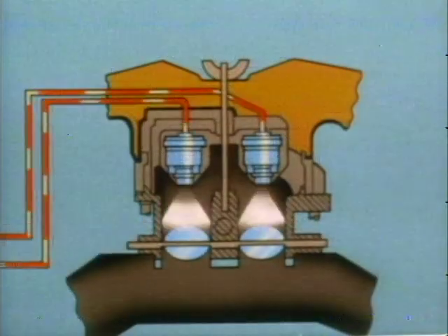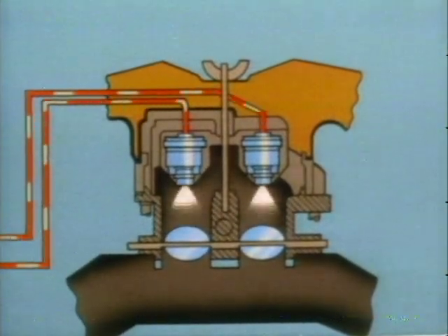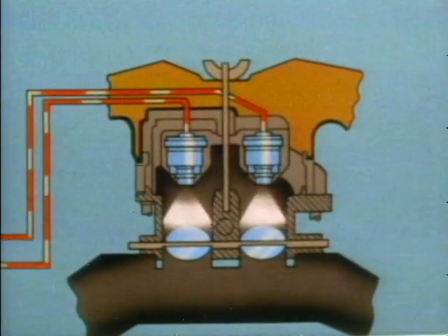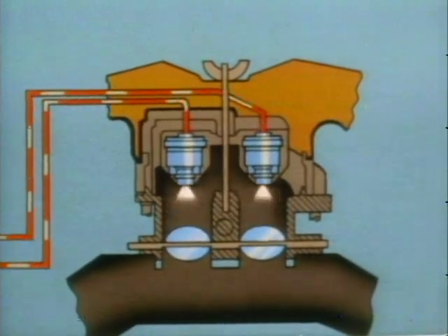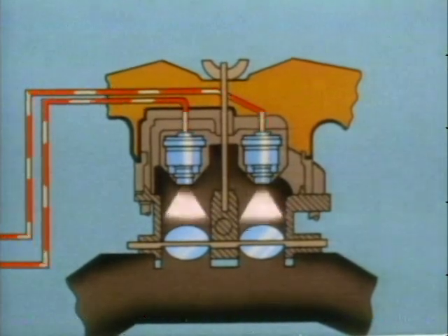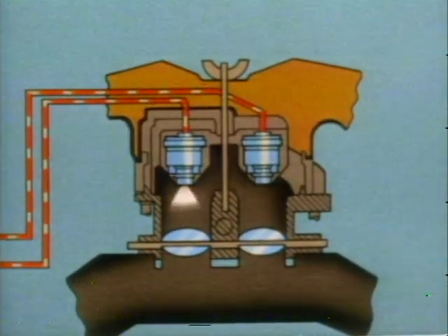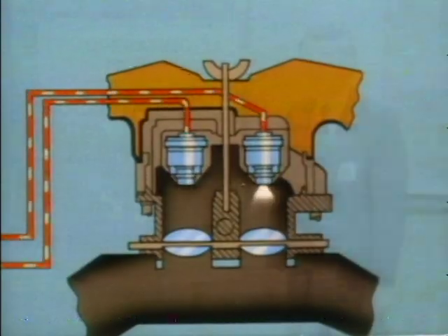The number of prime pulses is dependent upon coolant temperatures, with more pulses being delivered at lower coolant temperatures. When priming, both injectors simultaneously inject fuel at a fixed pulse width of 10 milliseconds. Once these prime pulses have been delivered, the ECM begins alternating fuel pulses with the width or on-time length determined by the numerous factors discussed under pulse width.